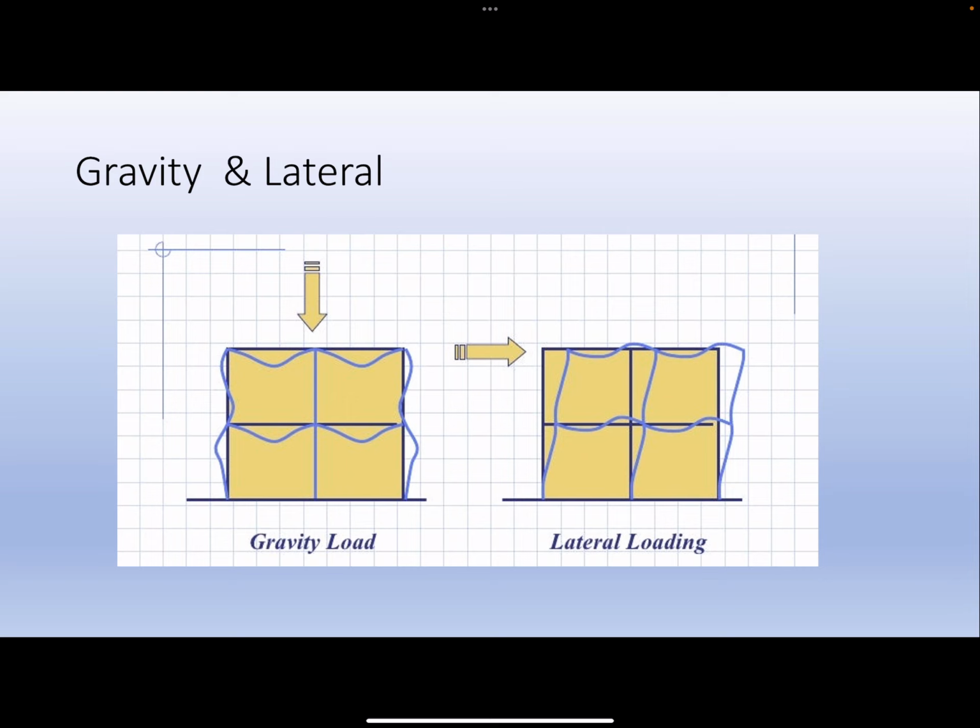So what we do is we separate our analyses into looking at just the gravity loads and the system that's going to support those loads, and then just looking at the lateral loads and the system that's going to support the lateral loads. And many times these gravity and lateral systems are integrated. Sometimes the members play a role in both systems, but we could treat them separately, analyze them separately, and that's how I'm going to set up our class as well.